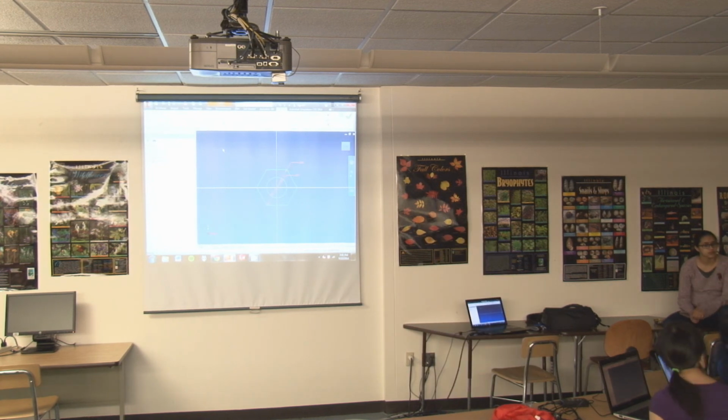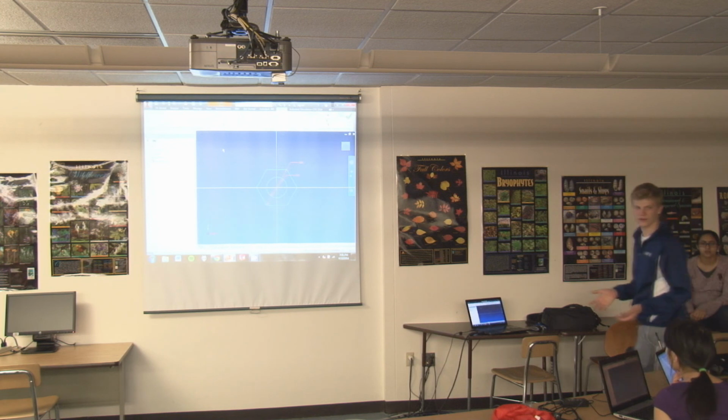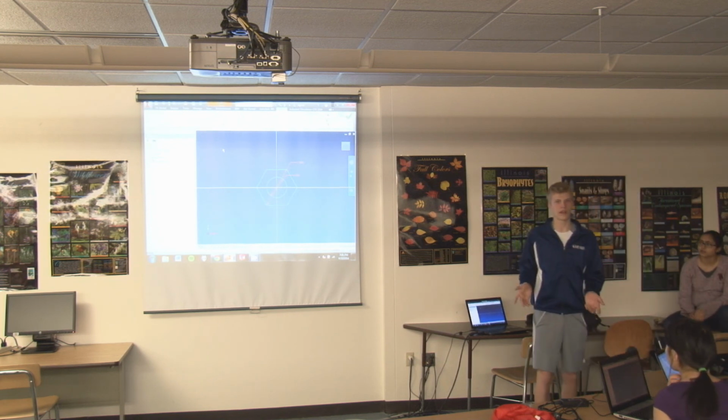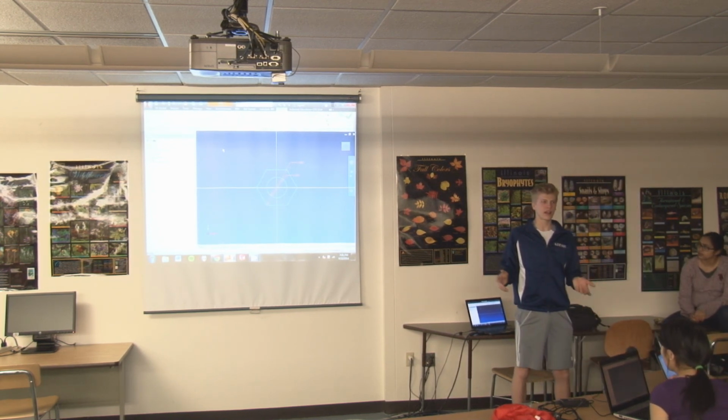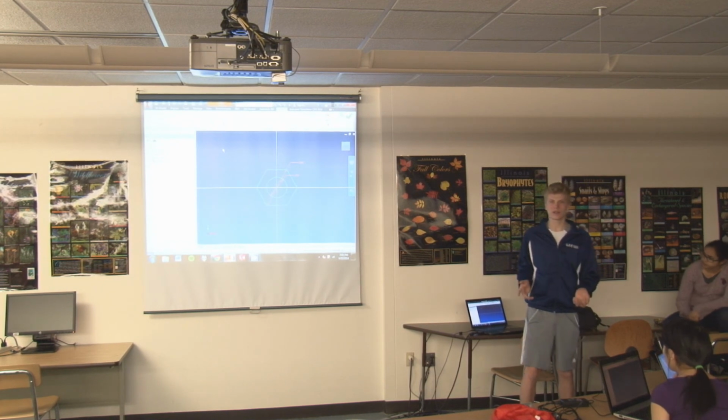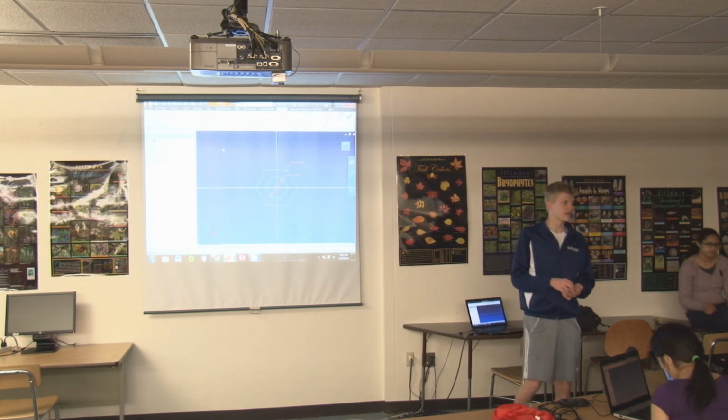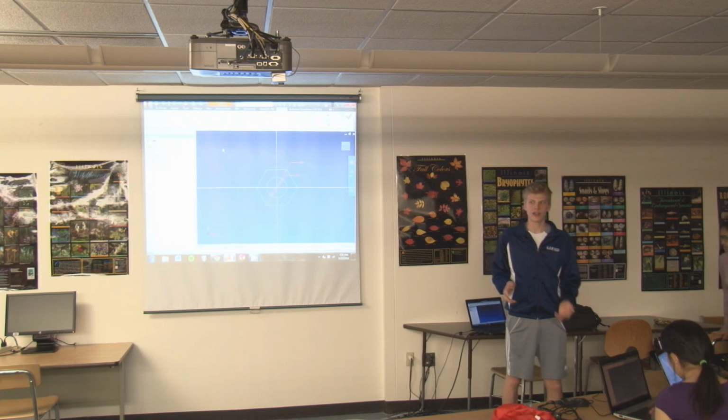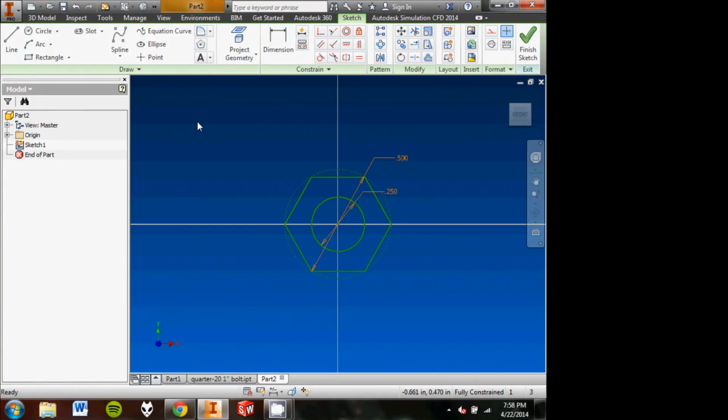Whenever something you think is constrained isn't constrained, the easiest way of figuring out why is just clicking on a point or a line or something that you think isn't constrained and dragging it and seeing what it does. And generally when you drag it around like that, you can figure out what's not working.